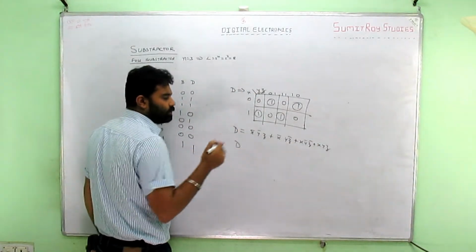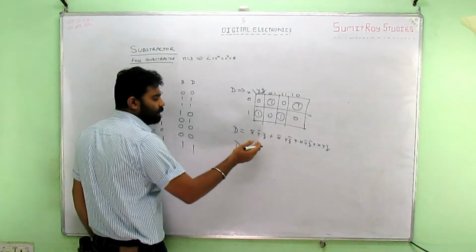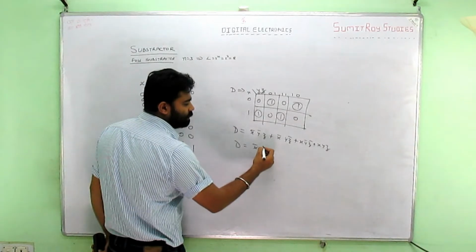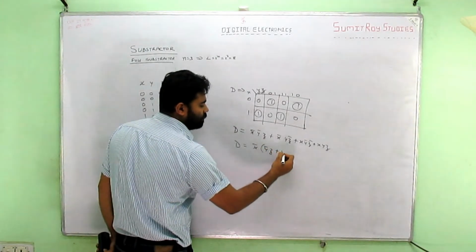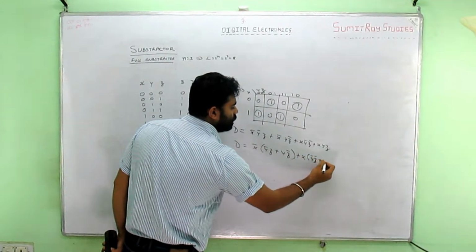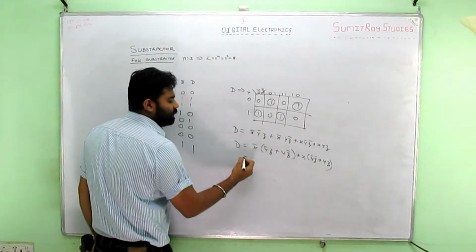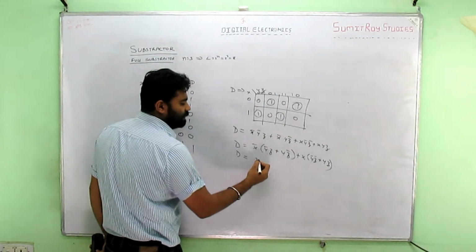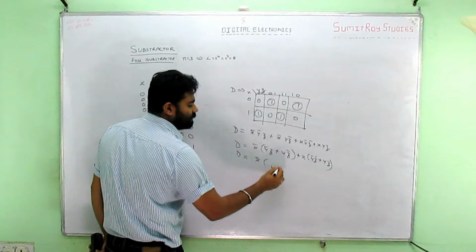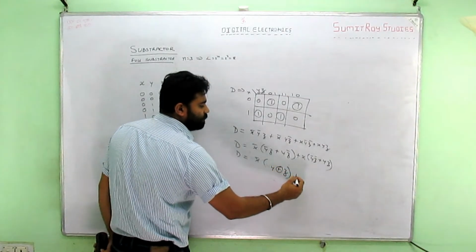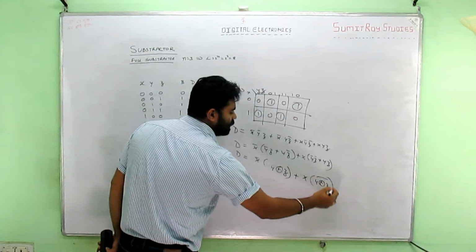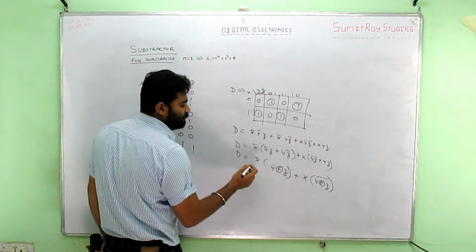This is the outcome of the K-map usage, and if further laws and theorems are utilized, then I can reduce it up to x bar yz bar plus x yz bar plus yz. If we go further, then it can be seen as x bar times y exclusive OR with z, plus x times y exclusive OR with z bar, that is, exclusive NOR with z.